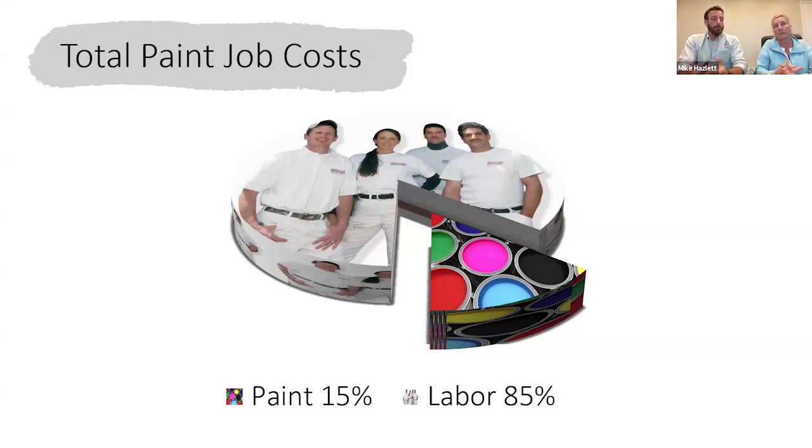When examining bids for a paint job for a project, it's pretty common, as seen here, that this might move 5% or something, but typically, don't hold me to it, your labor is about 80 to 85% of that bid, and your materials, or in this case, paint, is about 15 to 20.